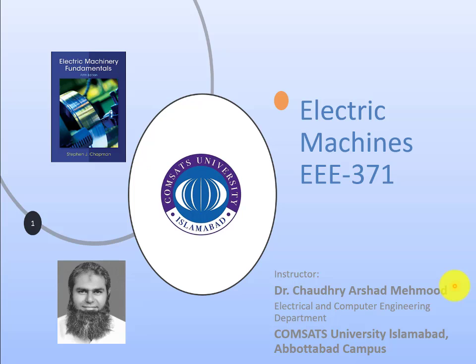So in this series of videos we are looking at the induction motor, and in this video we will continue with our topic of induction motor. In the previous videos we have seen how the induction motor works, and the most important phenomenon of the induction motor, which is the slip. Slip is the difference between the synchronous speed of the rotating magnetic field and the mechanical speed of the rotor itself. That relative motion is what actually produces the torque in the induction motor, and it is very much required.